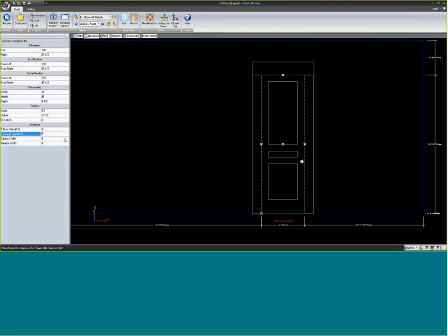If I go casing type number 3, here I can do things like the plinth width, so it changes my casing. I can change the reveal of the molding. Right now it's at 5/16, but let's say I want to go a 1-inch reveal. I can change that relationship of the casing to the plinths or the rosettes. I change the height of the plinths. Let's call them, for whatever, 14 inches high. I can make them 3 inches high. I can do whatever I want to do with them.